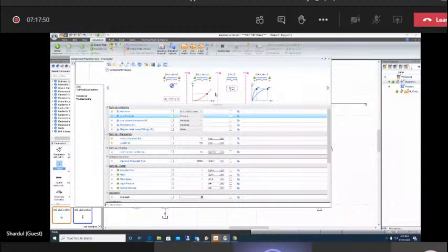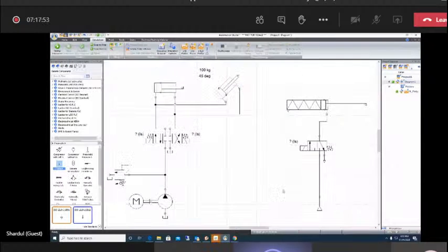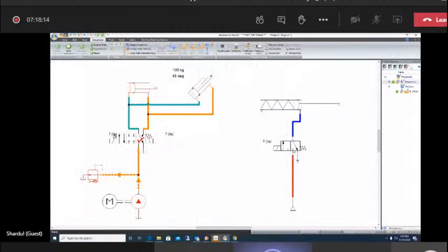So in this pneumatics part, I have taken a pressure source, that is a pneumatic pressure source. And if you see in the return line, I have added an exhaust. So this is an exhaust. It directly goes to the atmospheric air, whereas in hydraulics, we have the reservoir. Now, if I start the simulation, you will see that this is my pneumatic line. If I click on the left spool, the cylinder will retract, it will extend. So similar to what we saw in hydraulics, pneumatics also has similar components. The only difference is you have the pressurized air coming through the circuit here.